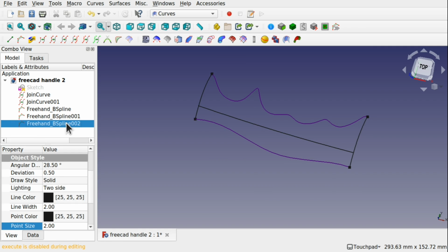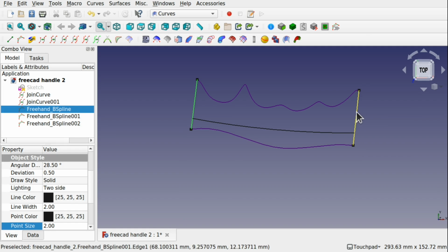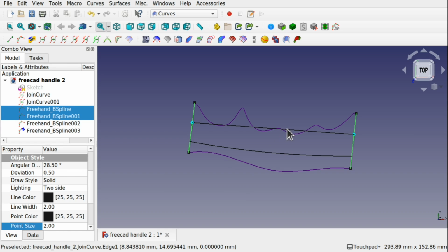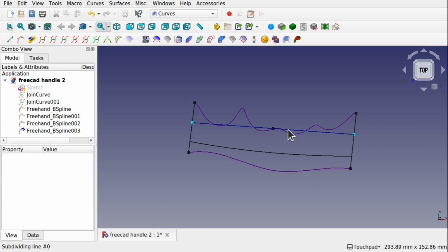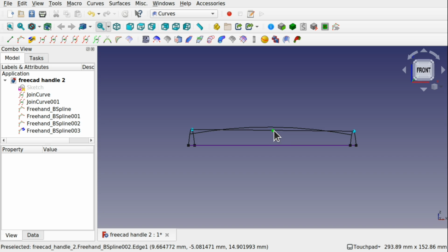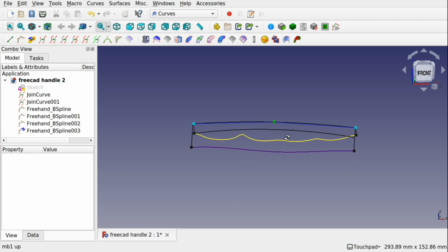Let's double click that b-spline. Let's add another one. So get ourselves positioned. Click the top of those two arches. Click the freehand b-spline, that places them across there. You can see they've got an aqua color. And I'm going to add another b-spline control point in there, like so. Bring it around to the front, and we'll just bring this up. Not too far, so click.